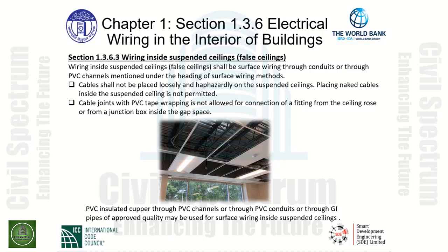PVC insulated copper through PVC channels or through PVC conduits or through GI pipes of approved quality may be used for surface wiring inside suspended ceilings.